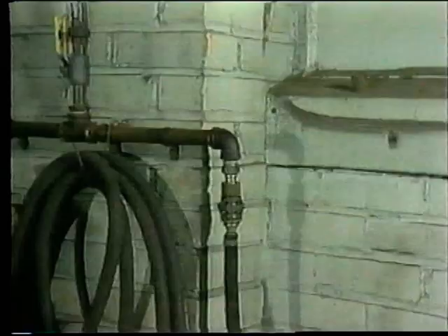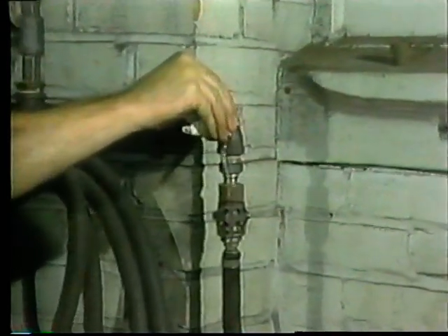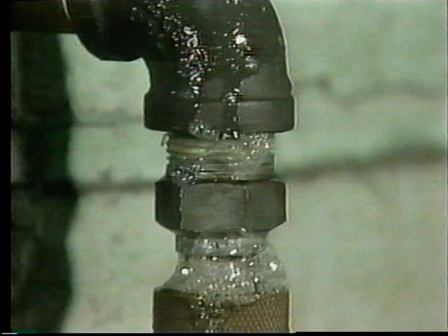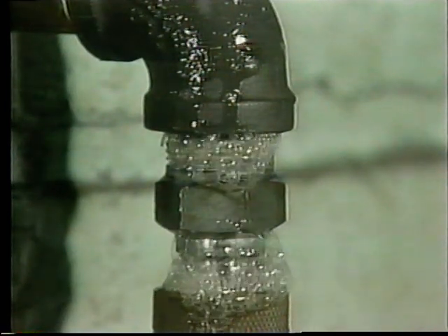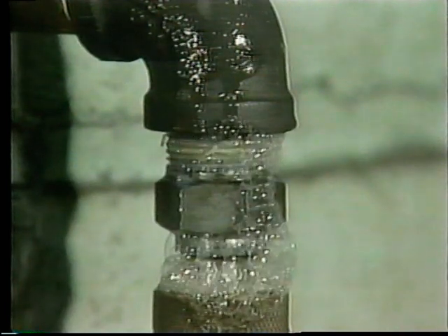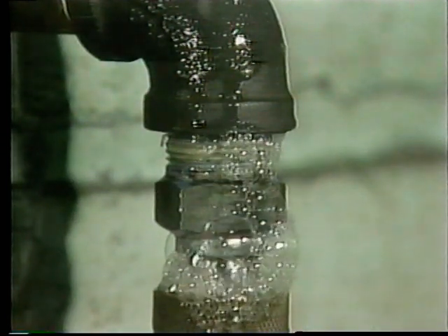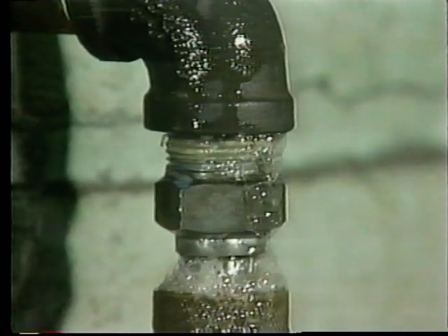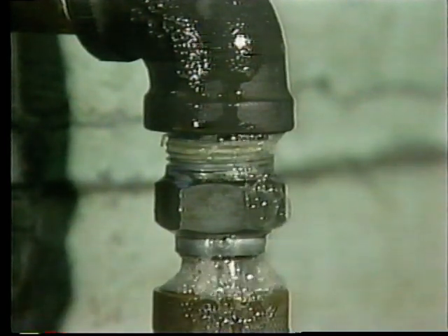I'm only kidding. Actually, for smaller or suspected leaks, soapy water, like this guy is using, or commercial leak detecting fluid can be very effective. The air escaping from the system will cause the fluid to bubble, as you see here. The method works just like checking for a leak in a bicycle tire.